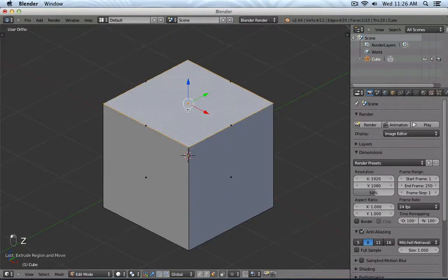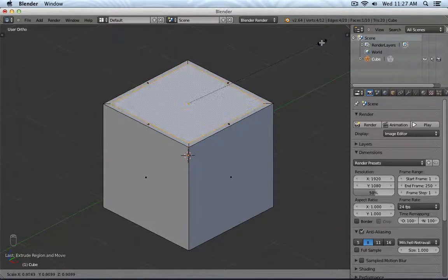So just as a heads up, when you start learning Blender and you see those black rectangles on a line, by accident you have extruded something. Only because you see a line doesn't mean that there's no hidden face. Anyway, at this point, as I said, I extruded and pressed Escape. I pressed Escape because I would like that face to remain where it is, and then I press S for scale, and then slightly move it in, for example.